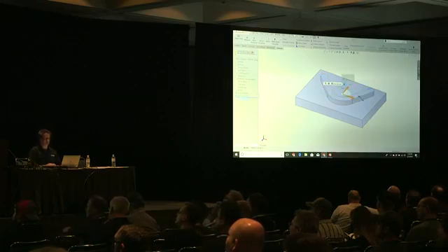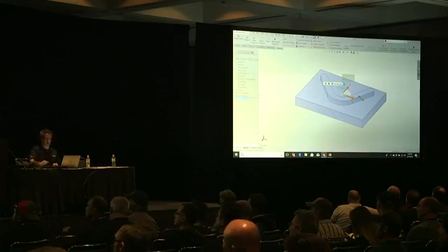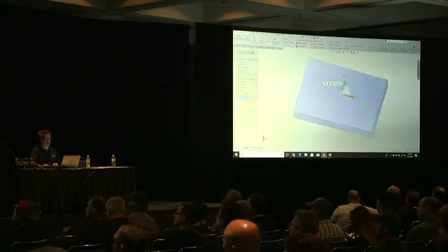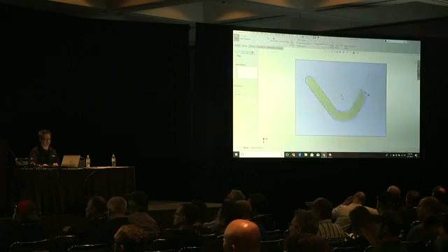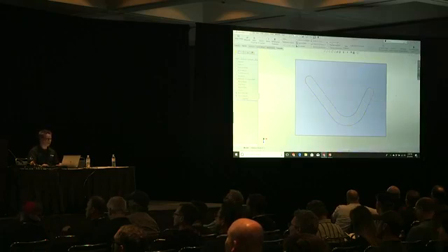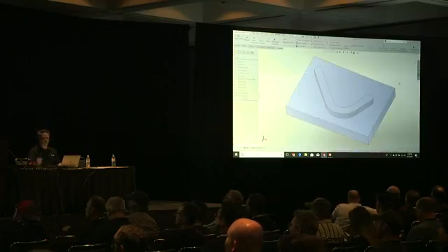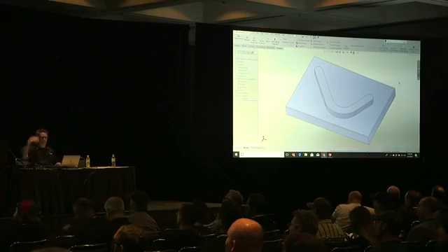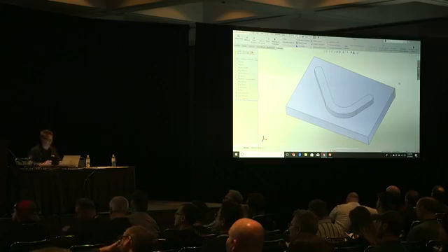When you hit sketch, because it shows part, body, feature, face. If I hit on my part, drops down to sketch. I can come right up, edit the sketch, jump in and do my thing. If I hit D again, it brings confirmation corner down to my cursor. So I can just hit that, exit my sketch, and I'm done. So the way to think of D, it just brings top left, top right, down to your cursor. Everything's happening right in the middle of the screen or wherever your cursor's at.